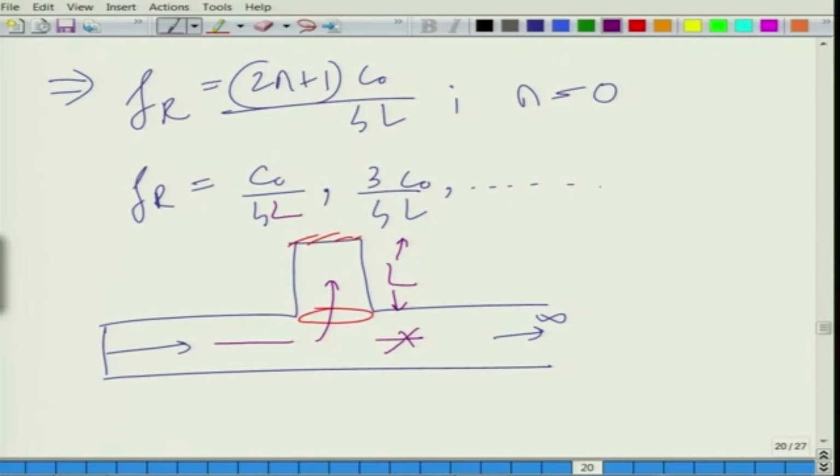That is the path of least resistance, what most of us do. So, basically all the acoustic power goes in along the side branches, and very less power is transmitted downstream. These are also called quarter wave resonators, because for certain frequencies given by C naught by 4L and its odd multiples, all the acoustic power goes in the direction of the duct, and very less power is transmitted. So, using this principle you can achieve certain tonal noise control.